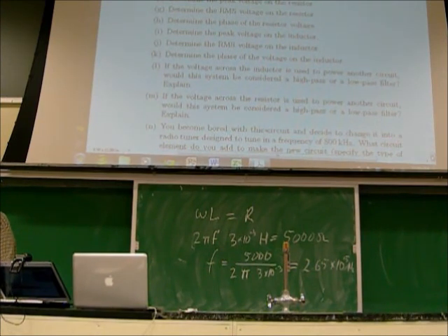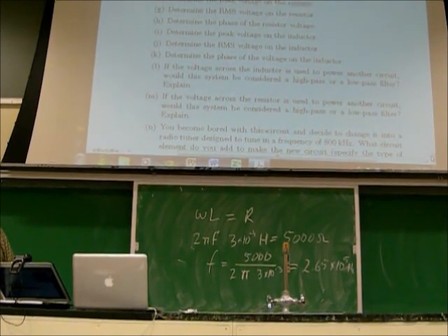But anyhow, in such a speaker, people will talk about crossover frequencies, because the lowest frequencies go to the woofer, the highest frequencies go to the tweeter, and in between goes to the mid-range. And in order to get a speaker with uniform response, you have to adjust the crossover frequencies that go to each of the three speakers. And you do that with filter circuits. This frequency would be the crossover frequency. Higher than this is considered a high frequency. Lower than this is considered a low frequency for this filter.